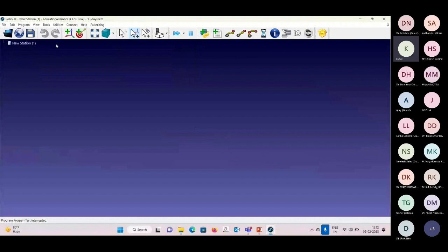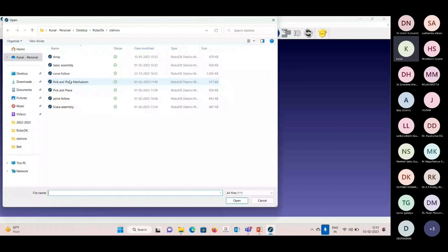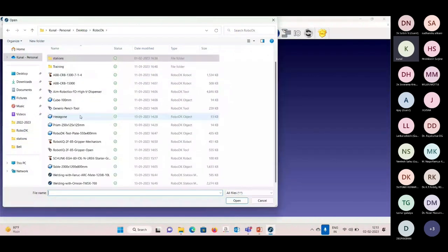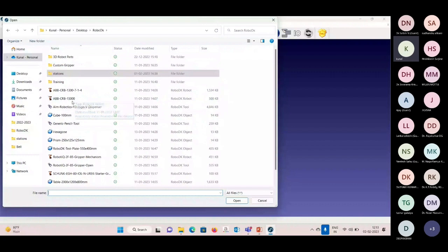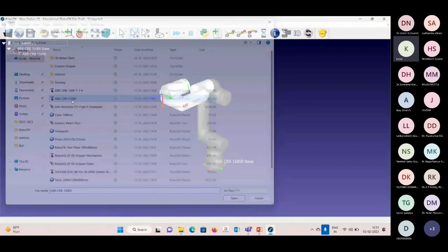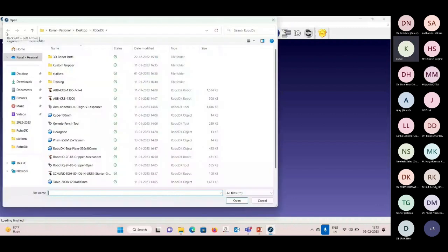We have done that. Now I have also done it for curve follow. Here you can also have a function for curve follow. If there is any program for following a curve, usually in weldings, you need to follow a particular path. For selecting that path, here is the option of curve following. So I will attach a dispenser tool for this. I have attached a dispenser tool.